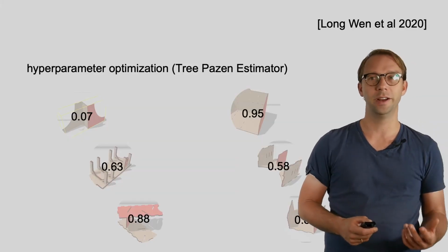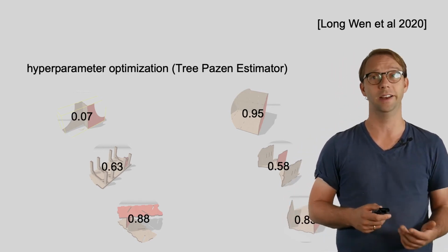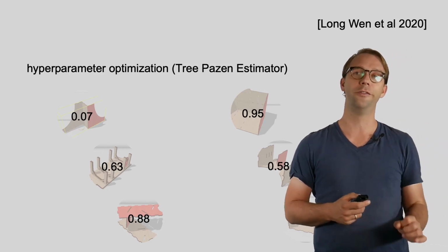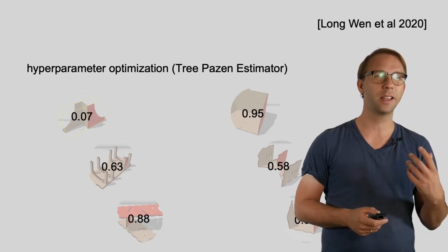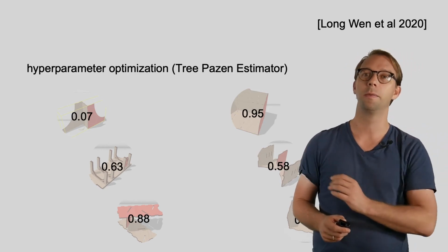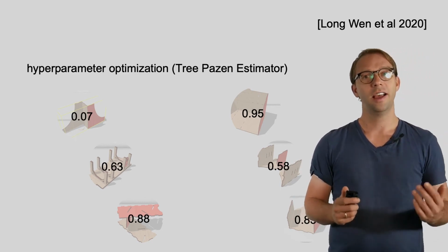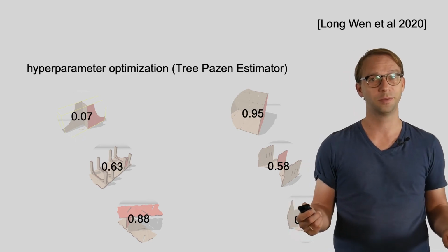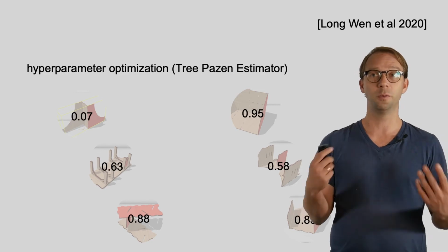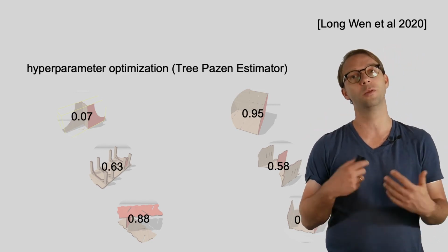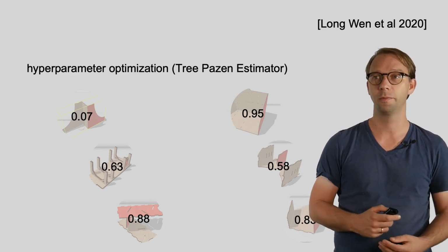To tune the weights of the heuristics, we used hyperparameter optimization based on the tree-structured Parzen estimator as proposed by Long Wen in 2020. This algorithm converged after feeding around 1000 assembled states as input. Intuitively, we had expected to see a much higher score for intersections here. But the truth is, we aim to save computational resources when scoring plates, as AutoAssembler runs the scoring many times. And therefore we find false positives when looking for intersections, which is why the hyperparameter optimization assigned a lower weight to the truth of the intersection finding.